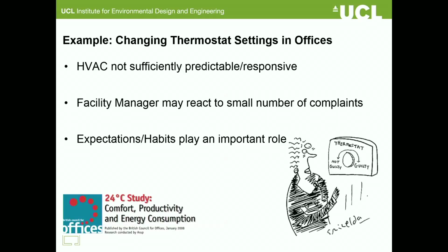If we consider a relatively easy example, a low-hanging fruit of saving energy without negatively affecting thermal comfort, is the idea of raising thermostat settings in buildings. One of my PhD students has been looking into this idea: can we raise the cooling set point of UK office buildings air-conditioned to 24 degrees, following the BCO recommendation? And now this was based on a report from Arup, and in turn all of the studies in this field, I should say, are based on observational data.